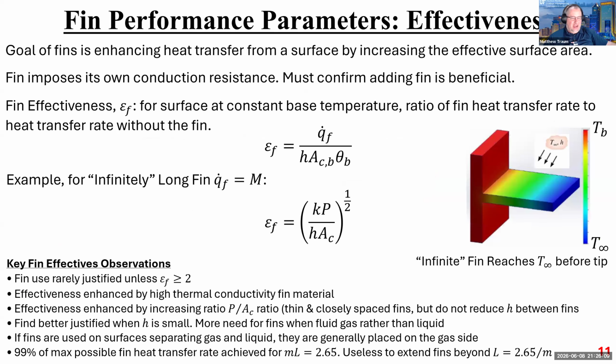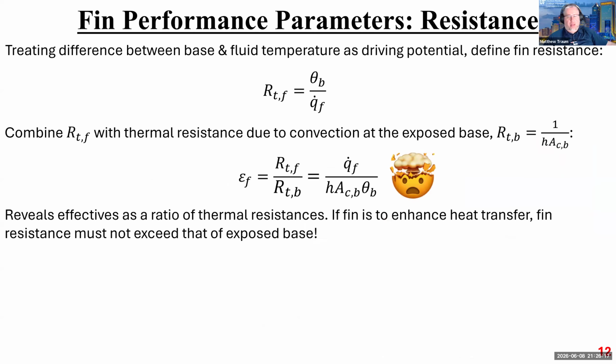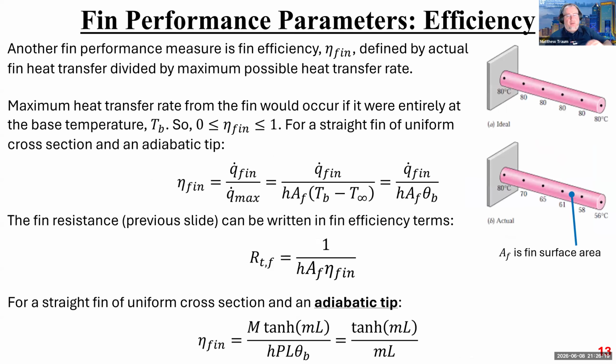And like I said, it's usually a rule of thumb that we only will put a fin in place if that number is greater than or equal to two. Okay. All right, so let's talk about another fin performance parameter. This one is the fin efficiency.